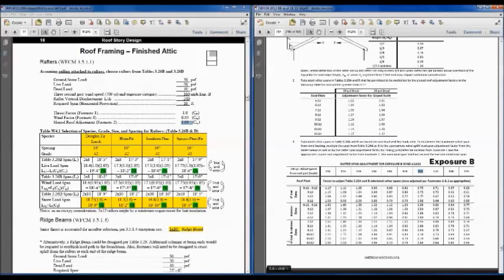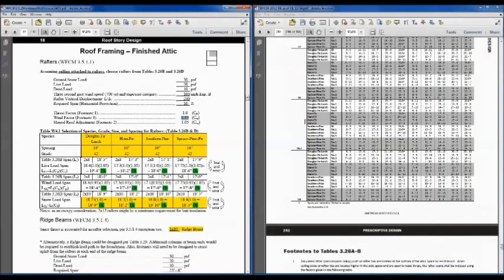and for the 7 and 12 roof pitch, there are all kinds of different roof pitches here that you have to look at, but for this particular example, 7 and 12 is the only option you've got, and that gives us an adjustment factor of 0.95. The commentary gives you background on these adjustment factors. For time purposes, you're just going to have to trust that the answers we're pulling out of here are right for this example, and you can look into the background on your own time.